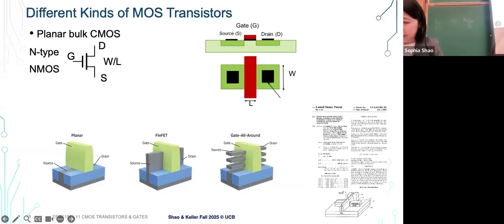So here, when we talk about the channel length, for most of the planar technology, a lot of the techniques people are using is to shorten the channel length so that things can flow faster, right? And also denser. You can have more dense transistors being fabricated. But when we get to the 3D technology, in particular FinFET, it's very hard to do that because you can only shrink so small, right? When you get very, very short channels, there are a lot of non-ideal effects. It's very leaky. There are lots of behaviors related to short channels.